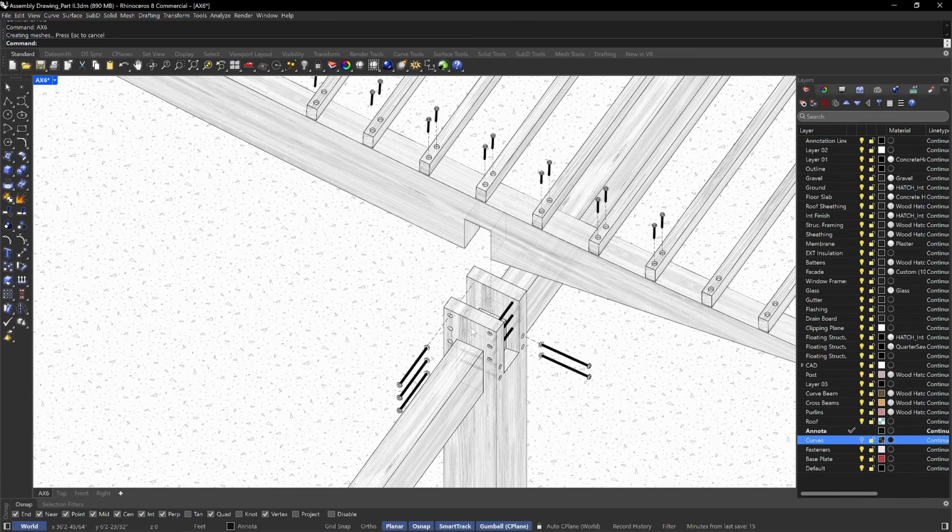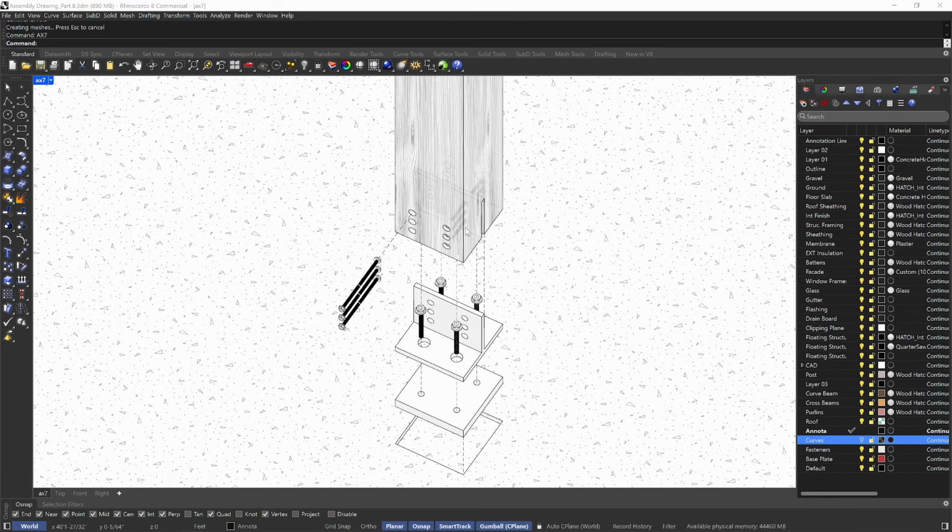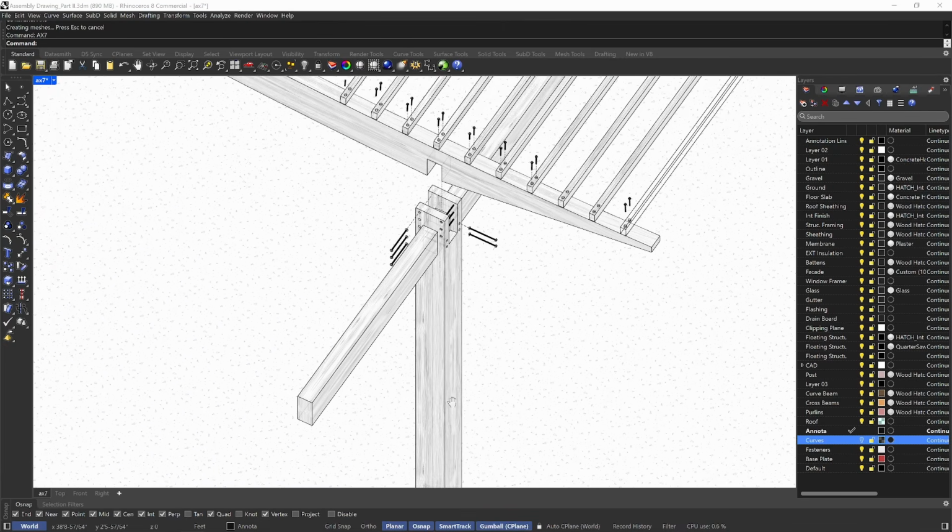And so you can extract many drawings from this one design that you have. So instead of recreating multiple drawings, you can use your one model to create maybe 6 or 7 or as many details as you like. So for example, this is like a post detail that's exploded, showing the beam and the post and the cross beams and the purlins for the roof and all the fastening connections. And this exact same drawing, we can go in and we can show like the base foundation detail, for example, like down here. See? So this is all one drawing.